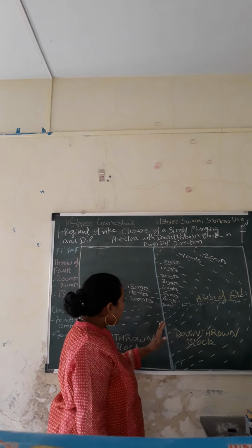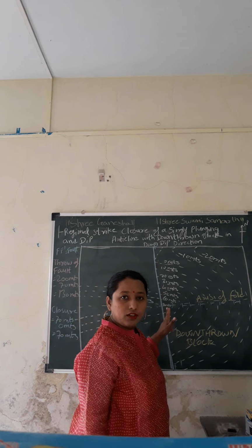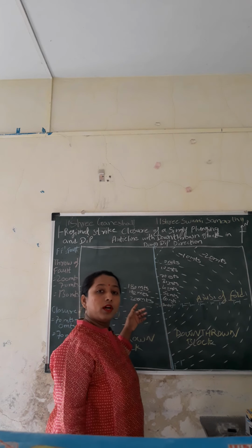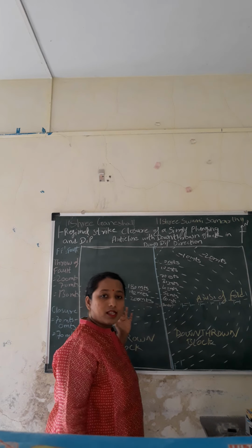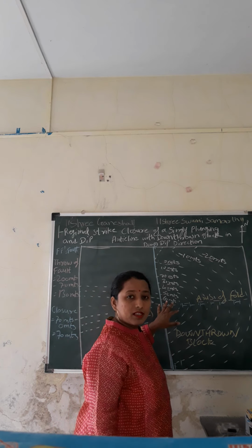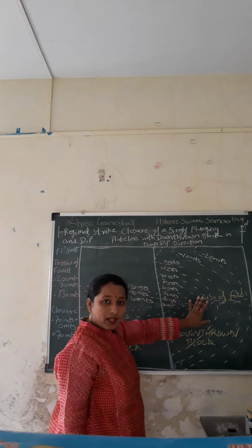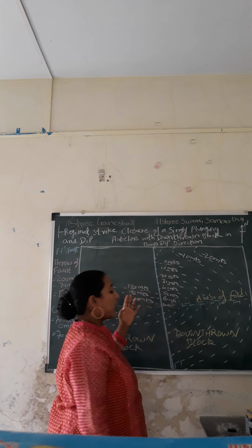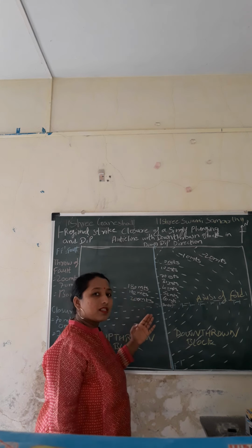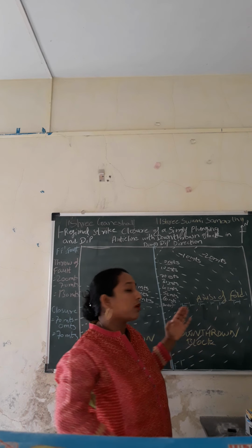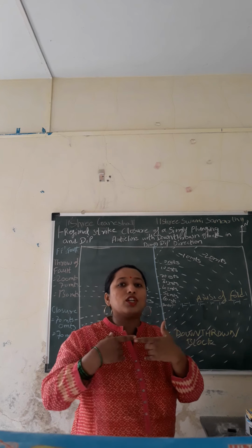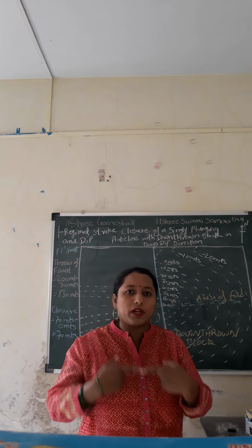Fine. Now here we get to see that the 70 meters contour on one side of the fault is coming in contact with the 200 meters contour on the other side of the fault. Similarly, the 60 meters contour on one side of the fault is coming in contact with 190 meters on the other side. The reason why we are discussing this, you guys must already know, is because we find out the throw of the fault by seeing which contours exactly meet one another.